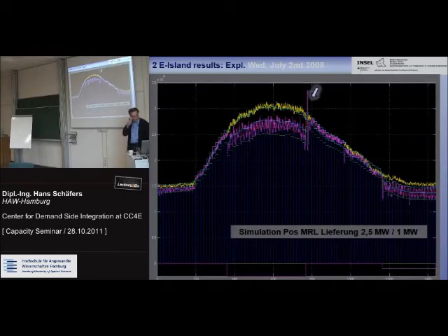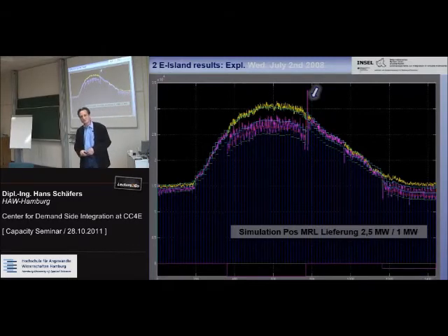Now this is an example for a reserve capacity delivery, starting here. And then we said, okay, if we want to make sure to deliver the right amount of energy, the upper limit should be the distance between the old schedule and the upper allowed limit, and it should reflect the amount of energy that was delivered by the system.